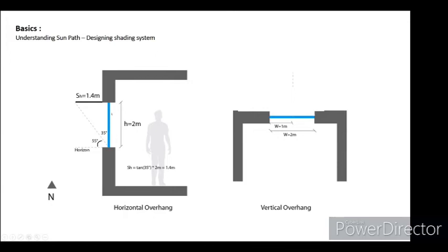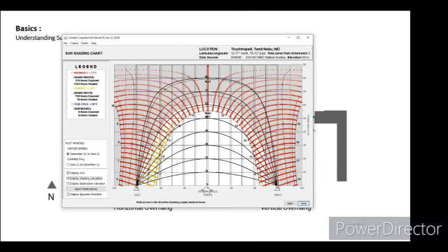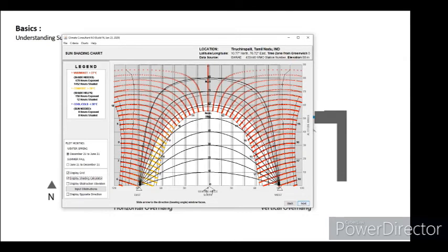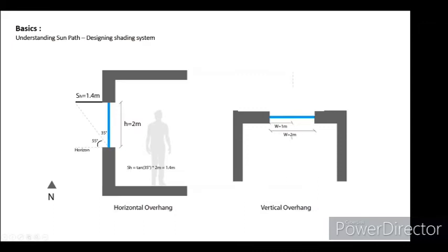Similarly, a south facade also requires shading from the east and west. For example, let's say you balance this at 60, the radiation coming from the west, because we know that the radiation coming from the east after 55 degrees is hardly any, because of the cold, typically not winter, but let's say during December and January early mornings. But over here on the west, you can control the degree of the shading system. Let's say I'm putting it at 60 degree or 30 degree. That is what happens over here.